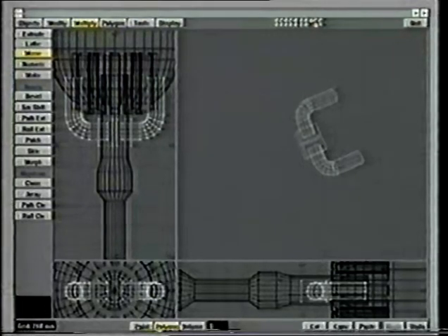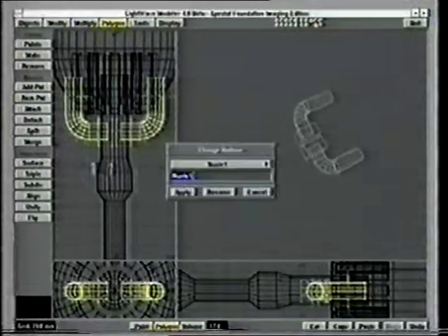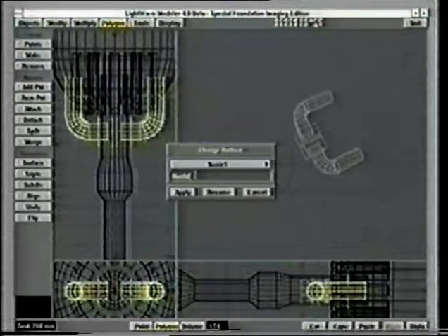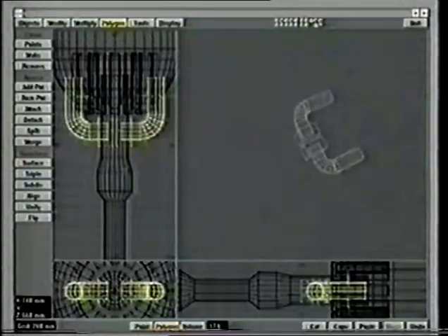One thing is missing though. I have not surfaced the tubes, so I'm going to do that right now. Let's use the select connected command, polygon, surface. Now, as the tubes in this model are bending all over the place, we're not going to be able to use any kind of image map based surface texture on them.